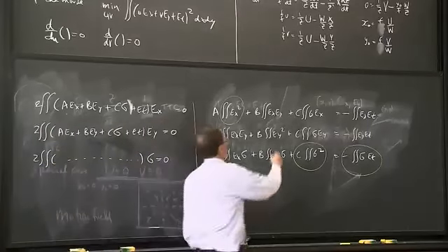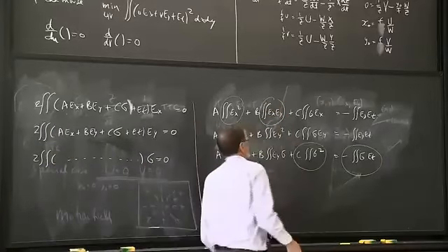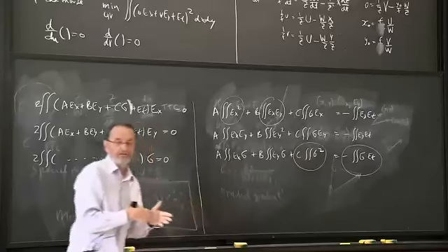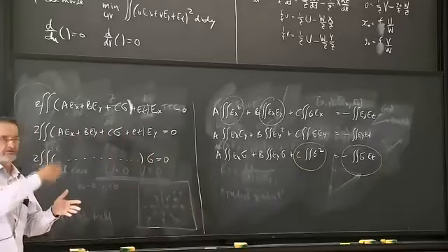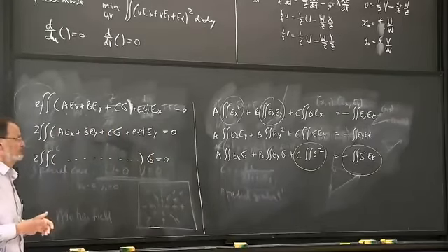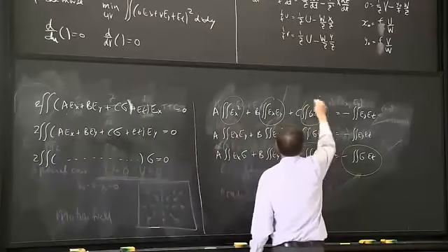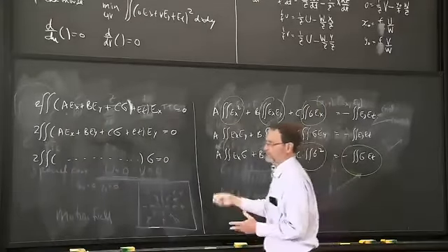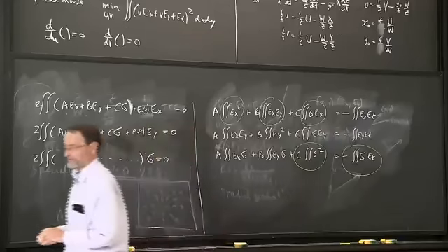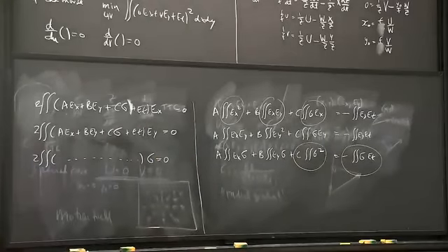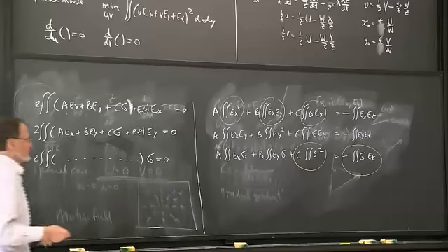Then we have another accumulator where we estimate ex and ey by looking at neighboring pixels in the y direction, multiplying those two differences. And then we have a third accumulator, and for g we have to do x times ex plus y times ey. And then we take the result, multiply by ex, and throw that into that accumulator.